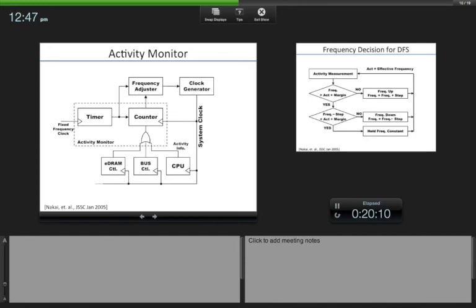Basically, what I was just saying is that the way you measure the activity is you set the timer, maybe you count the number of active cycles in a million clock cycle period. Timer is just a counter which is running off a fixed frequency clock. So you say, after so many million cycles, in that duration, let me count the number of times at least one of these was active. So that gives you an idea of how often or how busy the chip is.